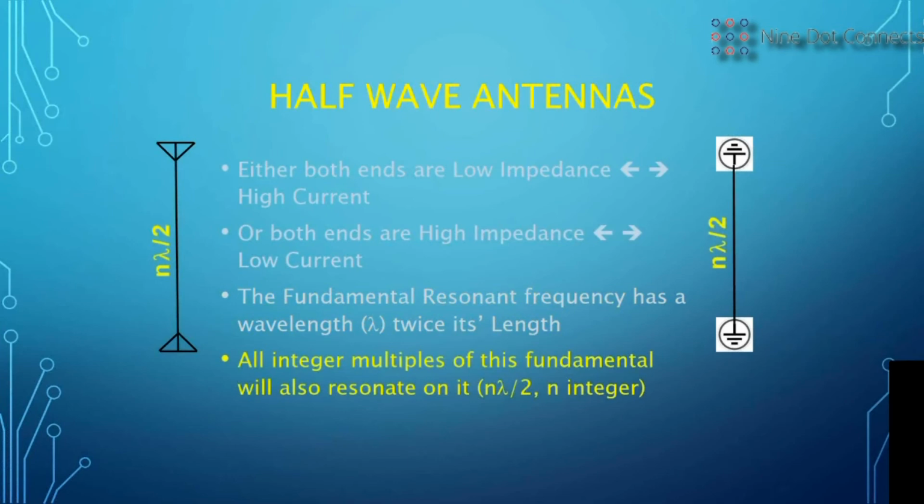So let's take a quick look at some resonant antennas. On the left, you'll see a representation of one which is grounded on the left and has a circuit feeding it partway up where the characteristic impedance of the antenna reaches that of the drive circuit for efficient energy transfer, and then it goes off to the end on the right where it is completely open and no current flows. That is the high impedance end. So that is in essence a quarter wavelength. You can see that again in the piece of PC board that is soldered that has the penny in it.